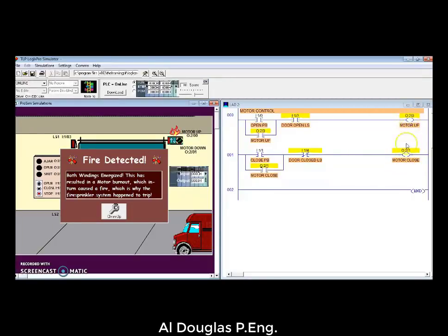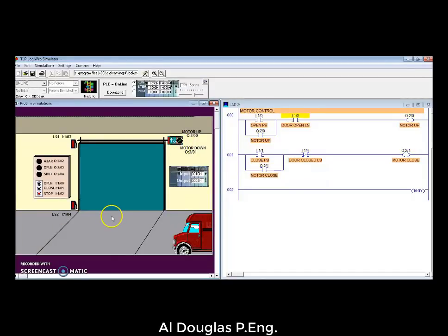This is a situation we need to avoid. So basically, I'm telling my motor to go forward and backward at the same time. That is a very bad situation, causes my motor to catch on fire. Now hopefully in a real world situation someone is figuring this out before the motor catches on fire and takes measures to prevent it, but a lot of times you are asked to put in logic to fix a real world problem that no one saw in the design phase. So we need to add some logic in there to prevent that from happening.